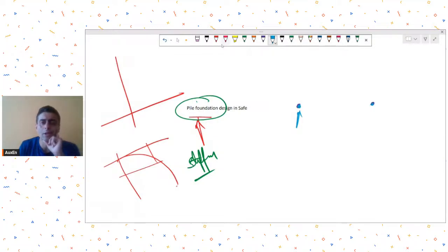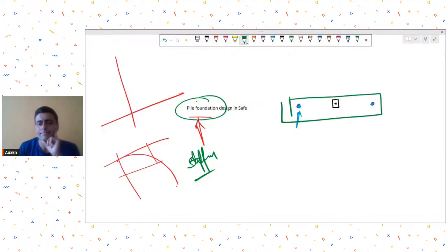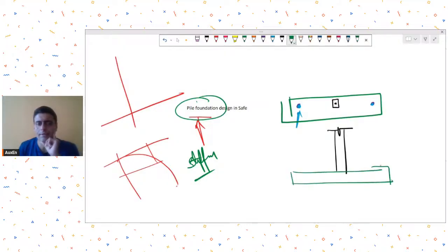For punching calculations we will need them, and let's say this is your column point which is going to be loaded. Then you make this type of a slab in SAFE. So section wise it will be like this is my column, and this is my pile cap, let's say, and these are the 2 points where I have assigned supports, and supports I have assigned spring supports, spring stiffness. Okay, once you do that, then you do the analysis.